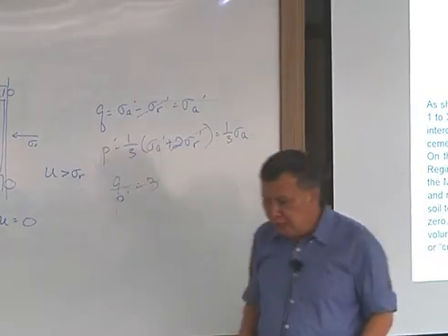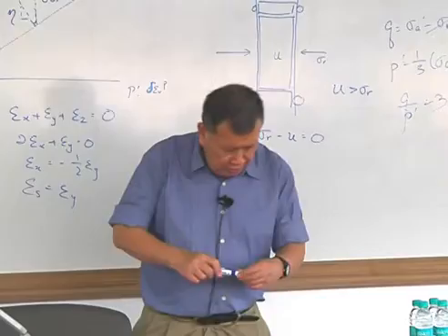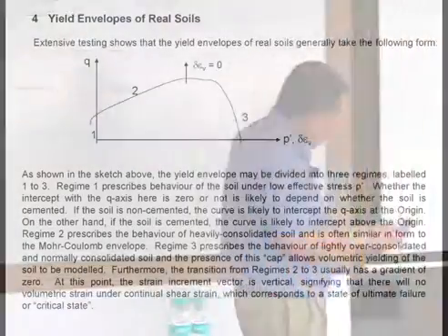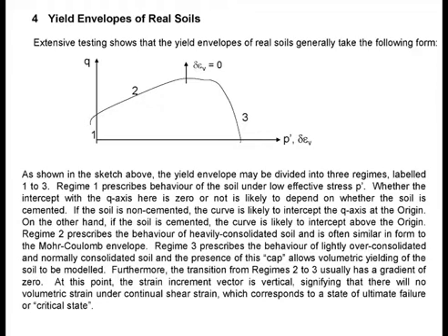So therefore, there is an imaginary line, okay, passing through the origin here with a gradient of 3 to 1 that your triaxial test sample will not go beyond. It will not go beyond. You're unable to bring it beyond. That is the limitation of the triaxial test. And we actually mentioned this in the 2014 paper in Soils and Foundations, Xiao et al. Because this is the limitation of the triaxial test. Because the rubber membrane will automatically detach unless you are able to glue it. But I don't see anyone gluing rubber membrane on the soil. So that definitely is out of the question.